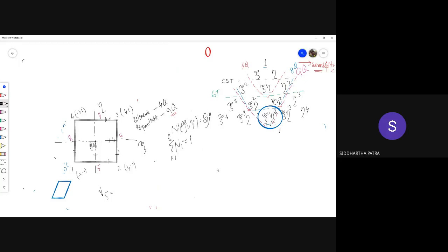Now if I want to construct, let's say, the shape function for the first node, you see that the highest order of the terms is cubic, which means I can take only up to 3 straight lines. The highest cumulative power of xi and eta is 3. Can you see that? Yes, sir. So the maximum number of straight lines that I can use to construct a shape function is 3.